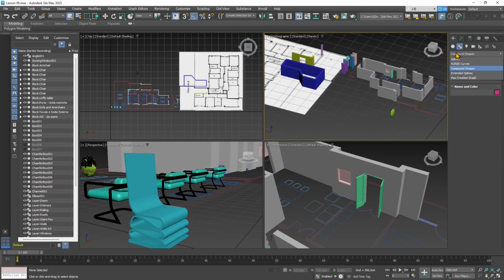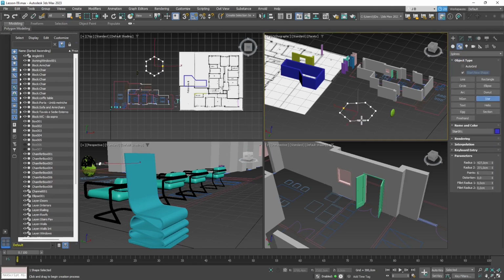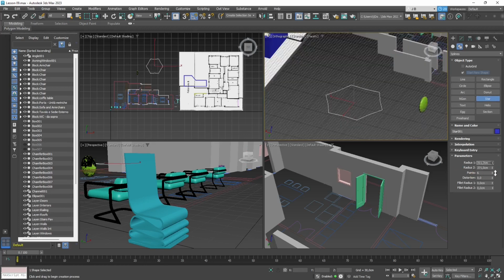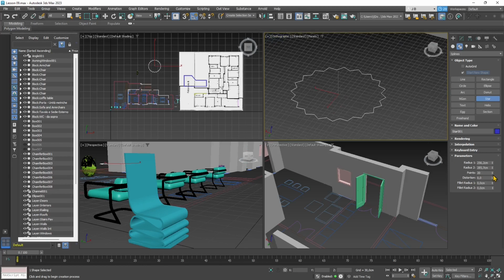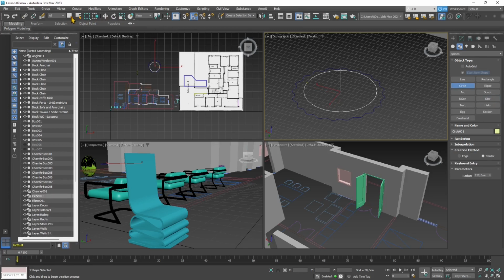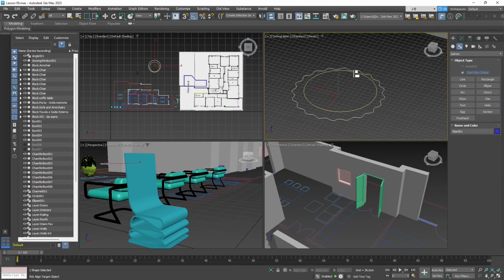And then we have another one, which is the loft. The loft is in the compound objects. So we need to create more profiles. When you use a loft, you're still gonna have a path, but not only one profile, you can add more than one profile, and you can create a lot of different shapes by mixing profiles. So I'm creating a star here and just rounding the peaks so that I can create kind of a bottle cap with this. So this is probably the easiest example you can do.